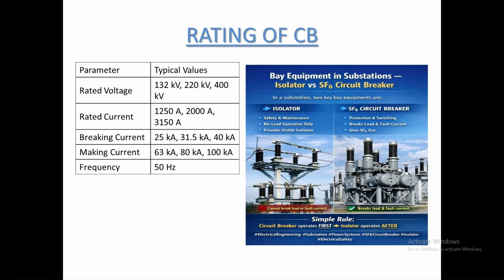If through some malfunction the contact has not opened, but we assume that the circuit is open, then the maintenance or the fault will not be extinguished. So there is a need for an isolator. We can refer to our isolator video for that.